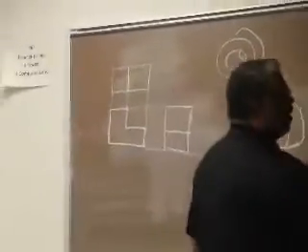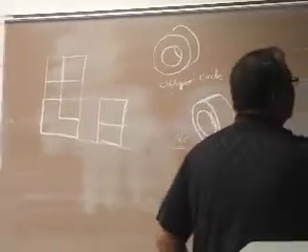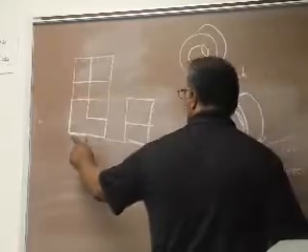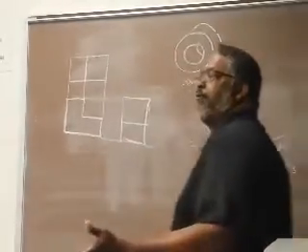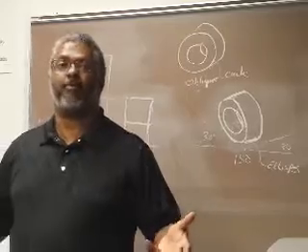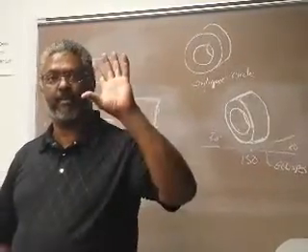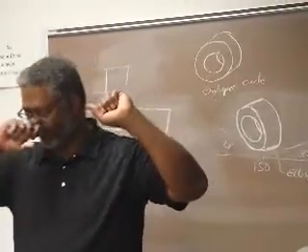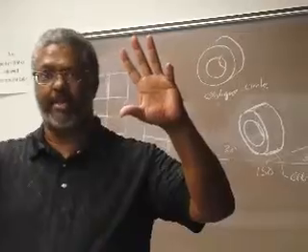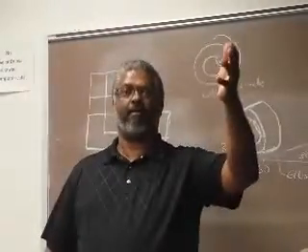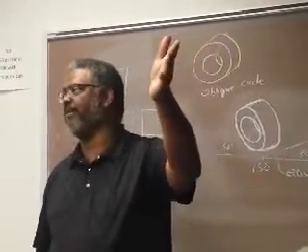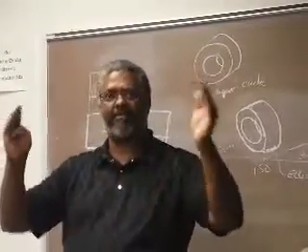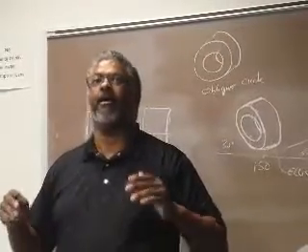Typically, when you're dealing with obliques, the view that you use to set up your oblique is the view that's more descriptive. A lot of times it's your front view, because when you set up a drawing, top, front, right side is in a standard arrangement. Such as if I'm looking at a car, then I know what the front of the car looks like. So that establishes the front, the right side, left side, top, bottom, and so forth.